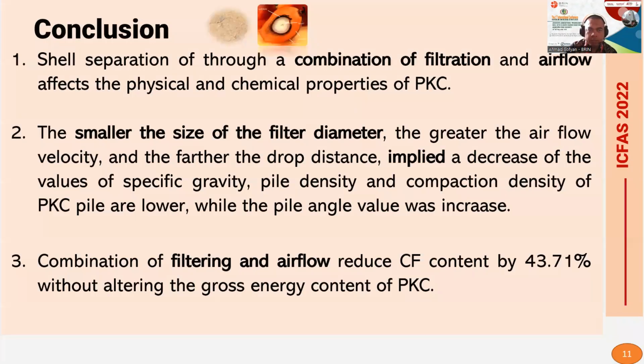It is concluded that shell separation by the combination of filtration and blowing technology significantly affects physical and some chemical properties of palm kernel cake. The combination of filtering and airflow technique reduces the crude fiber content of palm kernel cake by more than 40% without altering the gross energy content of palm kernel cake.